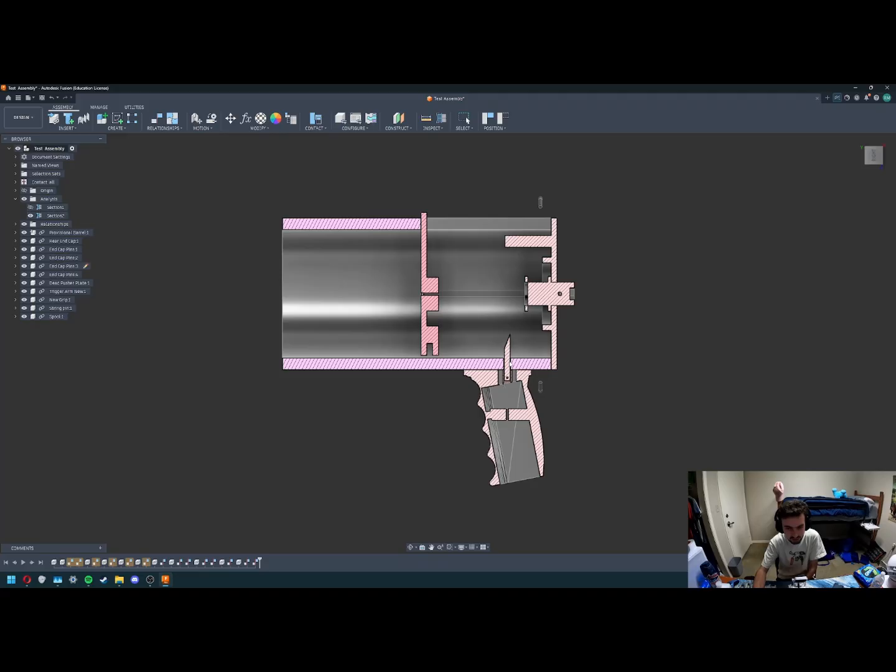And then as you can see, the trigger pin slots up, and as this moves back, it pushes it out of the way, and this will load for a second. The foam will push the pin back up and prevent it from moving forward. Obviously, Fusion's physics aren't the greatest, so it just knocks it out because it's easier to calculate. But yeah, that's the basics of how the bead launcher works.